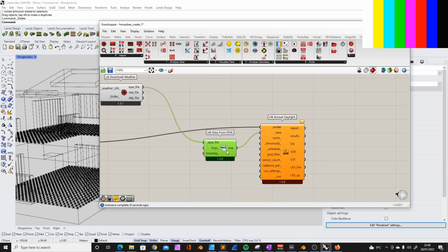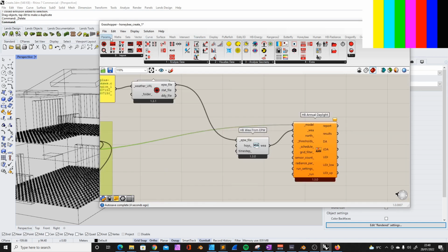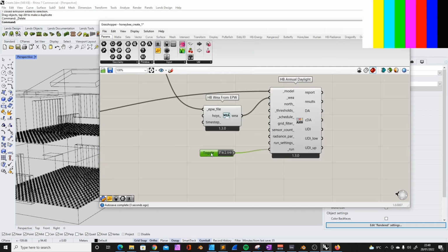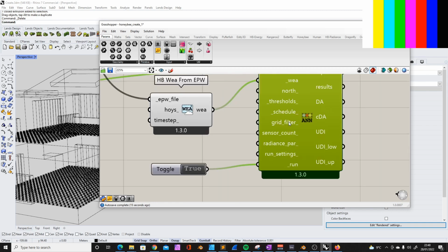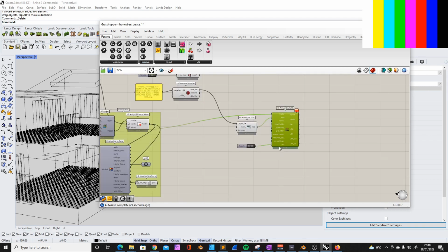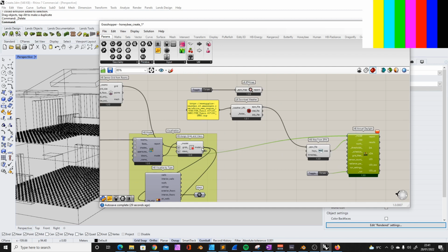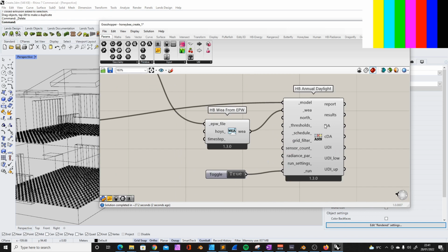And what else do we need? Because now, you see, if I don't apply the grid and I want to run that, most people have this problem: it first works, now let's run it, and now it doesn't work. And everybody's like, how does it work? And then they try the grid filter, should I apply the grid here or something? No, you need to apply the sensor grid here to the model. And then if you now put the model in here, then it starts to calculate. And now it's done.